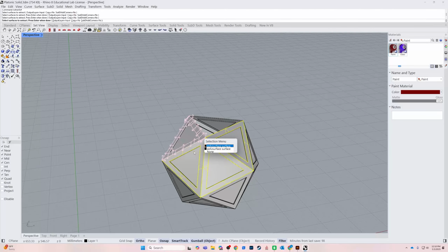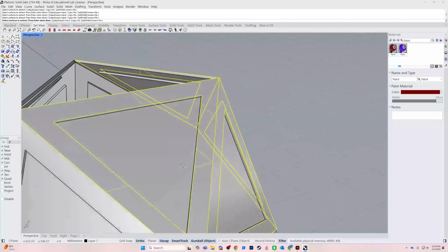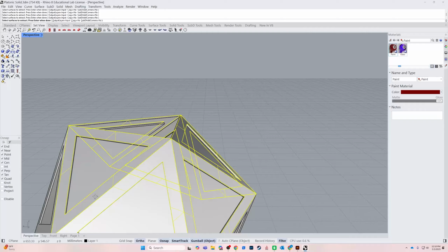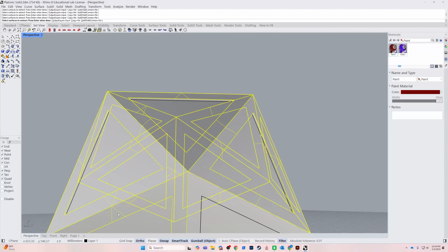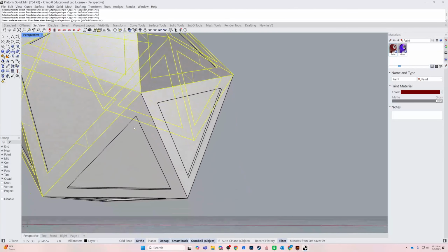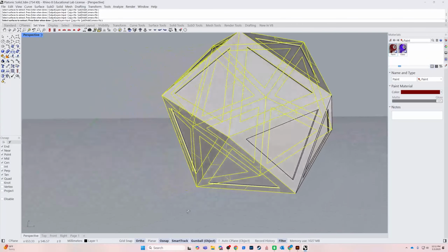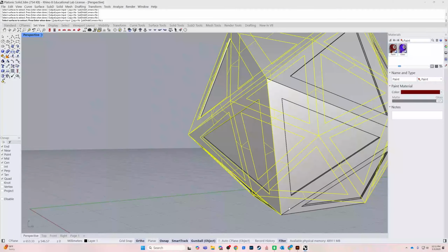Now you've got to be careful. Sometimes it'll say, hey, which one do you want? I want this one. You want to make sure that you're edge to edge, only getting those exterior ones. So I'm just clicking around here on all 20 sides of this exterior surface. All right, once you see them all nicely highlighted in yellow, we got that one too. Make sure you don't forget any of them. Then we can hit enter.